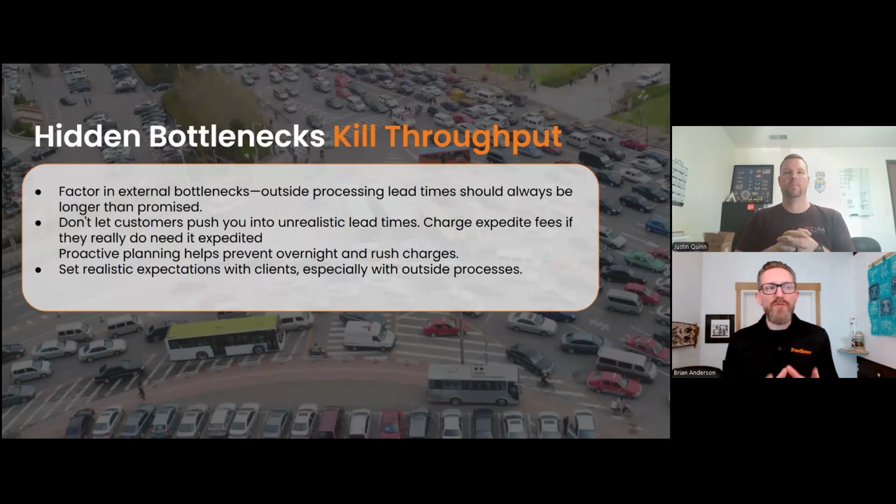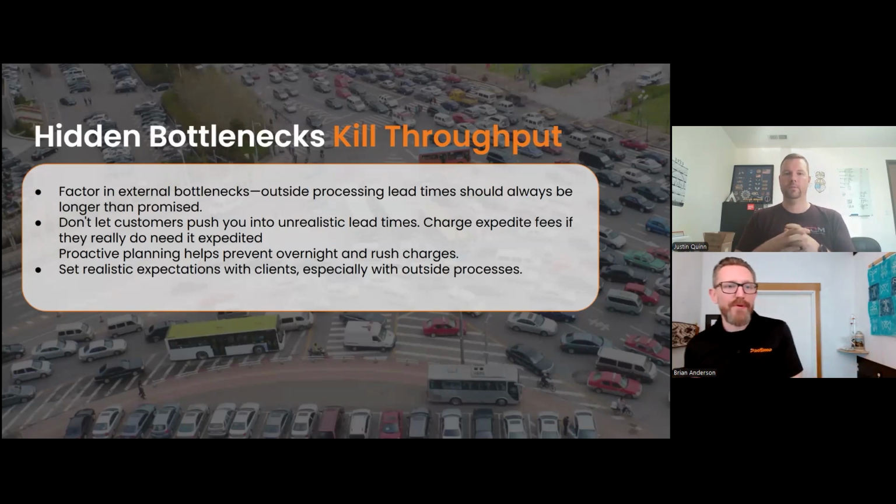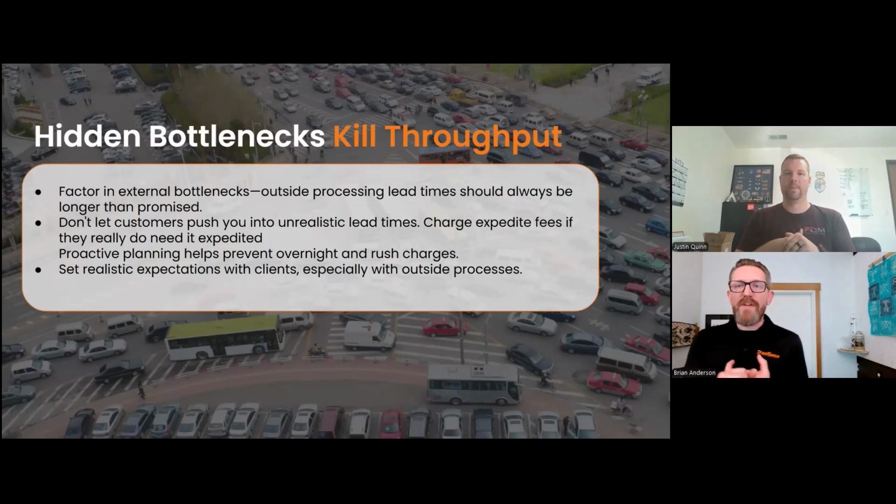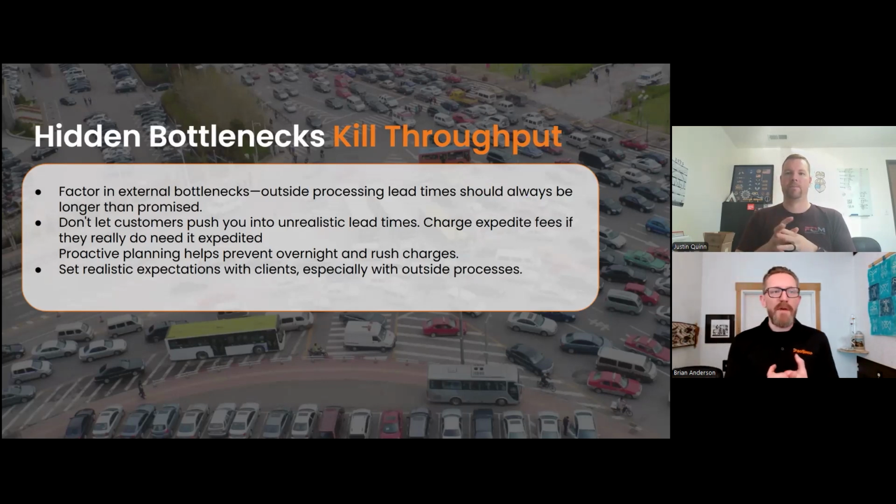If you don't understand the backlog or the workload of things that have to move through your CMM, and you quote the job understanding your programming lead times, your machine lead times, and even your vendor lead times, but you forget that you've got a massive backlog on the CMM and it's going to take an extra 3 days to get through, that's a really good example of a hidden bottleneck that you didn't account for in your system.